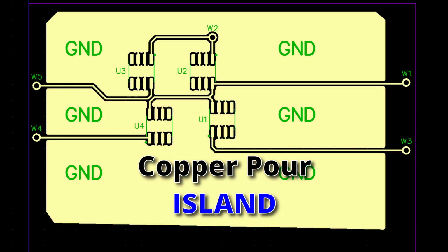So when we finalize the layout of the PC board, we need to discover these islands and take steps to allow the pour to be electrically connected to itself everywhere. This can be as easy as moving a trace or jumping a signal to another layer. Sometimes this is an impossibility, and we rely on a connection to its cousin plane on the other side of the board to make that connection.